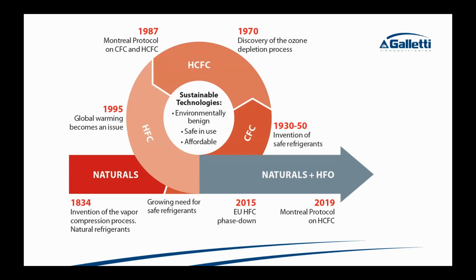So R290 for a cold climate like this, if you're using it for heating, it's pure propane. The purest form of propane doesn't smell anything like that, but it's a great refrigerant. You'll see all different brands have products producing 170, 180 degree leaving water temperatures, units operating down to minus 20 Fahrenheit or even greater, with very high COPs. So that's where it appears things will be going.